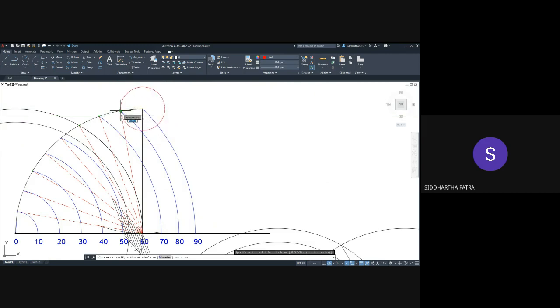So you can make a trial and error to find out the arc length which represents 10 degrees. Once you have figured that out, that is universal, so you can use that for the span between 60 to 90 degree, span between 60 to 30 degree, or in the span between 0 to 30 degree. So that is with the division of the arc.